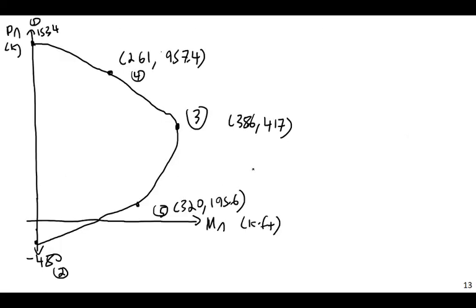So we're going to trim this graph at 1227. Even though the curve might predict up here, we're going to limit ourselves at line 6 at 1227. So I'm trimming the acceptable region. Assuming pure axial capacity might say we're good above here, but the code's never going to allow us to go over 0.8 times the axial capacity, even before we get to phis.